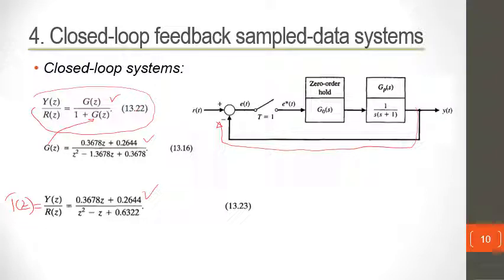This can also be done in the control systems toolbox. Look in your reference text where they create an example of a closed loop feedback system. You should see how you close this feedback. There's a single line that you can use just to close the feedback and get this transfer function.